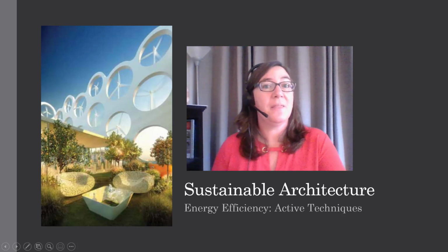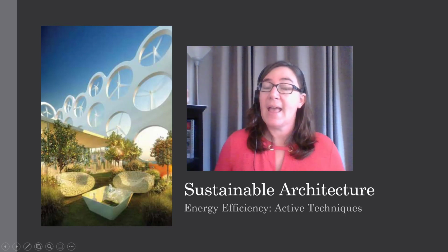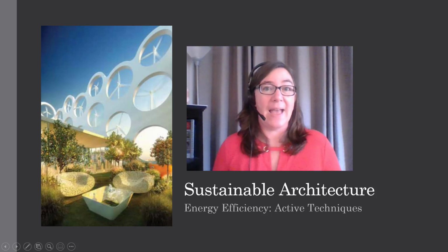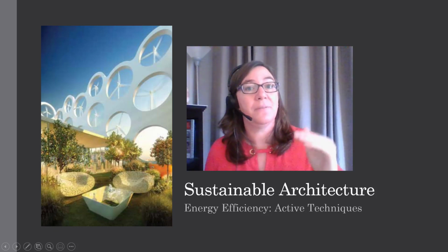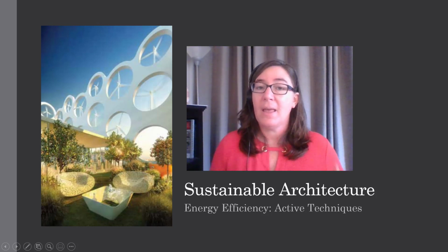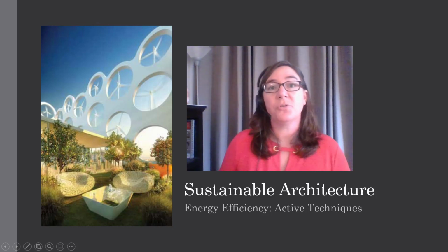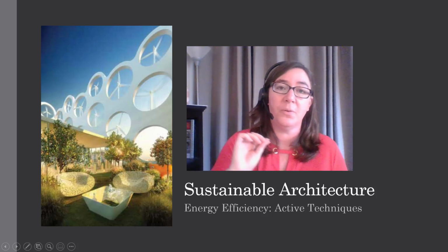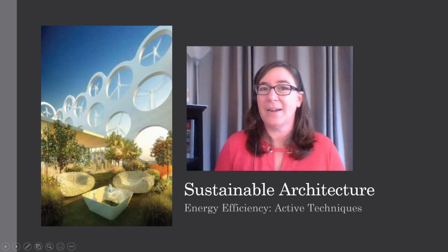All right, everybody. In this video, we covered the LEED energy and atmosphere category. We talked about the different energy efficiency strategies available and covered two of the major tools used to implement those strategies, and that's energy modeling and commissioning.